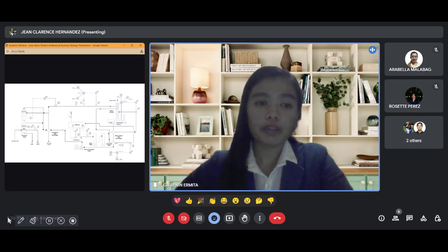So the glycol dehydration system operates through a meticulously designed network of 7 control loops, each precisely calibrated to uphold specific parameters and enhance the overall efficiency of the process. These loops, ranging from overseeing liquid levels in the contactor tower to regulating temperatures in the reflux column and skimmer, play a pivotal role in maintaining a continuous and controlled processing of wet natural gas.